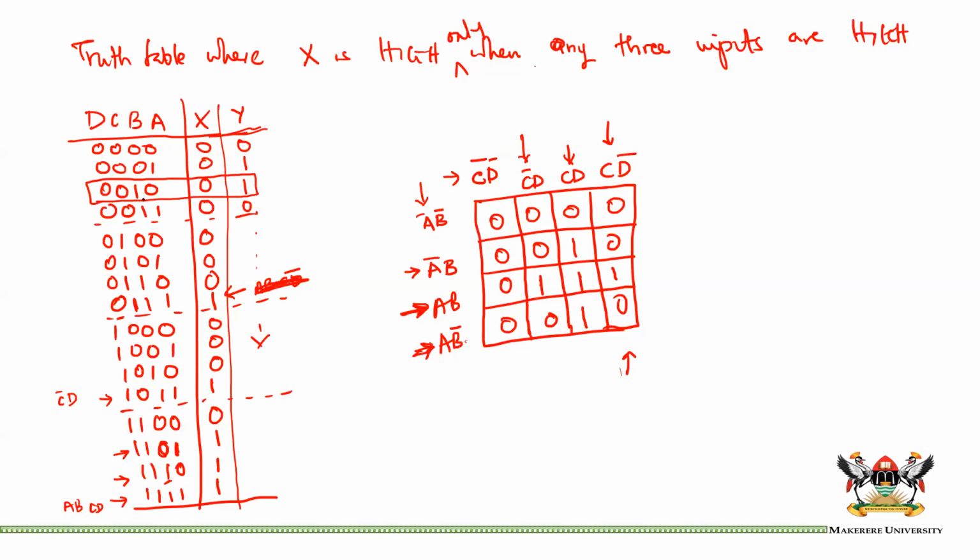And where we have a 1, you look at the states. A is a 0. So if A is a 0, it is inverse, right? And B is a 1. So B is in the 1 state. Then C is a 0, meaning that C inverse, and D is a 0. That means D inverse. So if a value is a 0 in these truth tables, we take it as an inverse. And if it is a 1, we take it as the normal form.